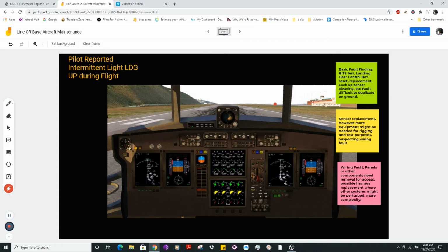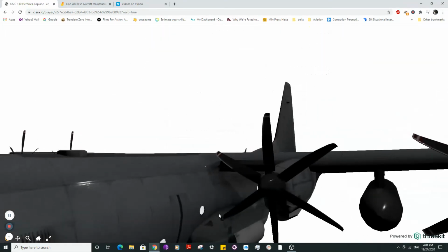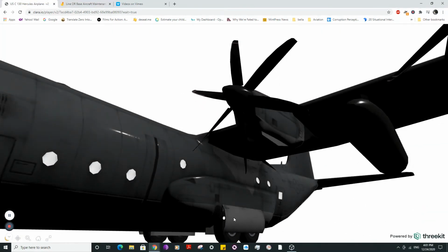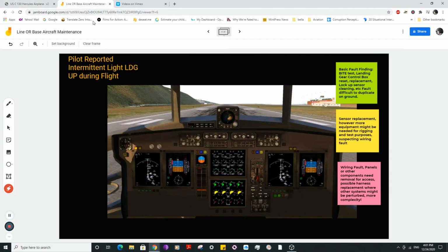You don't know. So obviously it depends on the maintenance organization. They normally take the route of consulting with maintenance engineering support and say, look, this is what happened. I could duplicate the fault, but I cannot find what it is. So we need to know. So let's say you just replace the sensor, and it wasn't necessary to open this panel, for instance, or to remove this panel here, sorry, fairing, and okay, you replace the sensor, off you go, and the aircraft will go back to service.